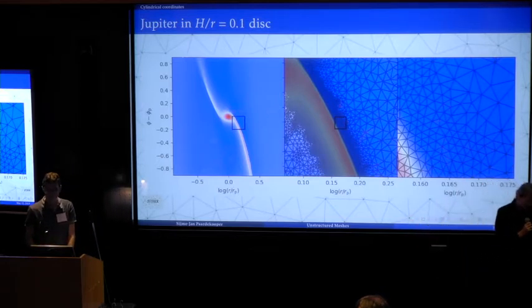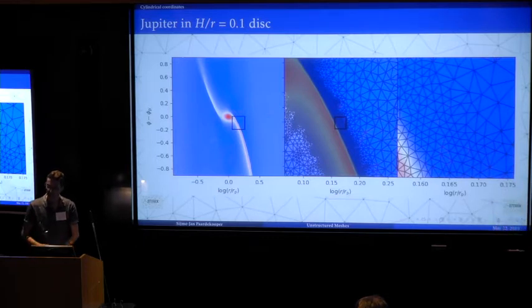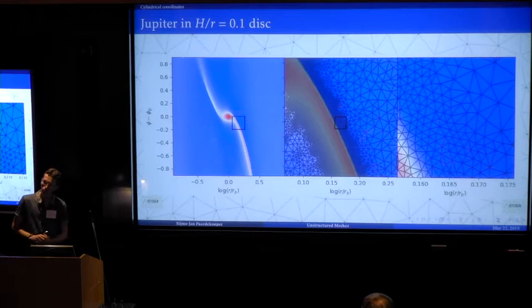I'm very sympathetic to this because this is geometrically natural, using simplices: triangles in 2 dimensions, tetrahedrons in 3. And those have a lot of advantages. Let's say you were doing, as climate people might, 2-dimensional flow but on a sphere, something topologically non-trivial. In addition to all the advantages you mentioned, you avoid the coordinate singularities which are inevitable with any sort of regular mesh.